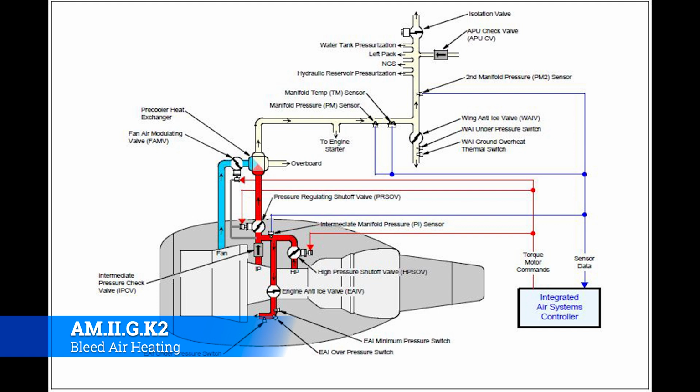The other thing to think about is that bleed air can also be responsible for a lot of fires, so this is something you want to take into account and remember. You have overheat sensing elements near all the pneumatic ducts, and they monitor the system ducts for leaks, because a leak on a bleed air system is what's going to cause your fire. There's also an automatic over-temperature and overpressure protection system that will flag any abnormalities to the cockpit. And there are pressure transmitters and even a gauge on the P5 panel in the 737 that show the right and left manifold pressures.